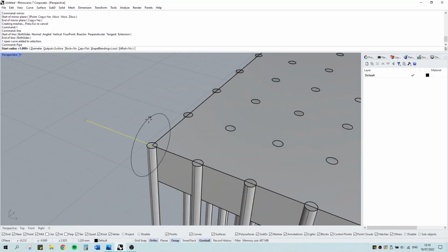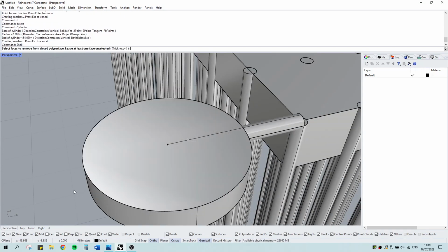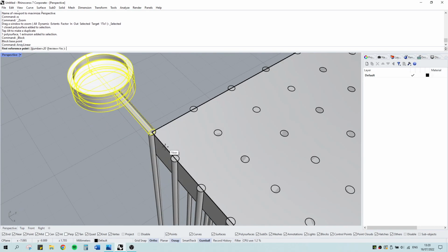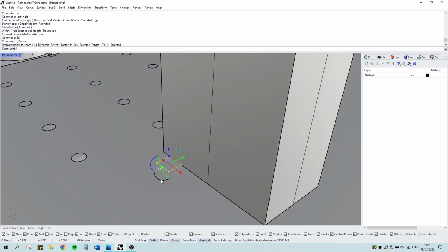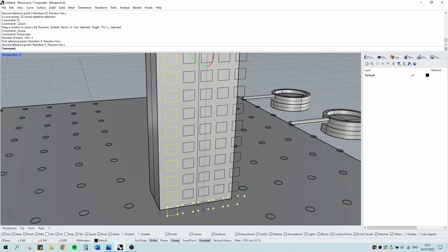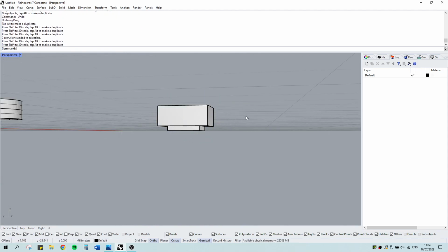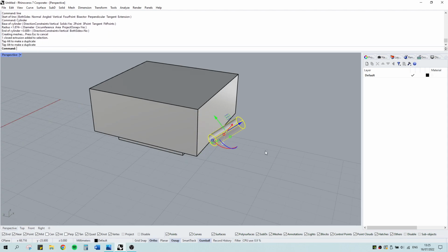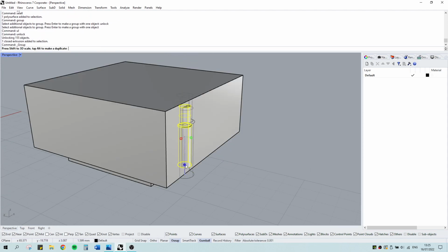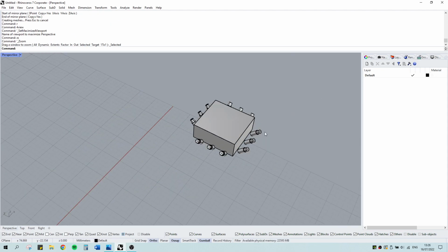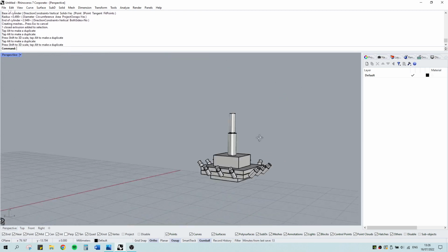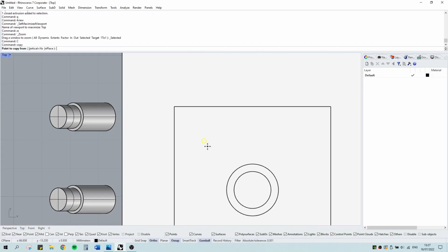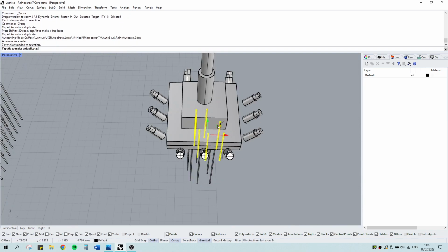Those are cylinders, using the cylinder command. Use the shell command to create some details for the cylinders, and array. Draw the box and use fillet edge to create rounded corners. The second module is basically just boxes and gumballing boxes and cylinders. I think the modeling logic is basically the same, but just with a bit of mirroring and scaling, and you'll get it done. Which basically stresses the importance of using gumball and mastering it.